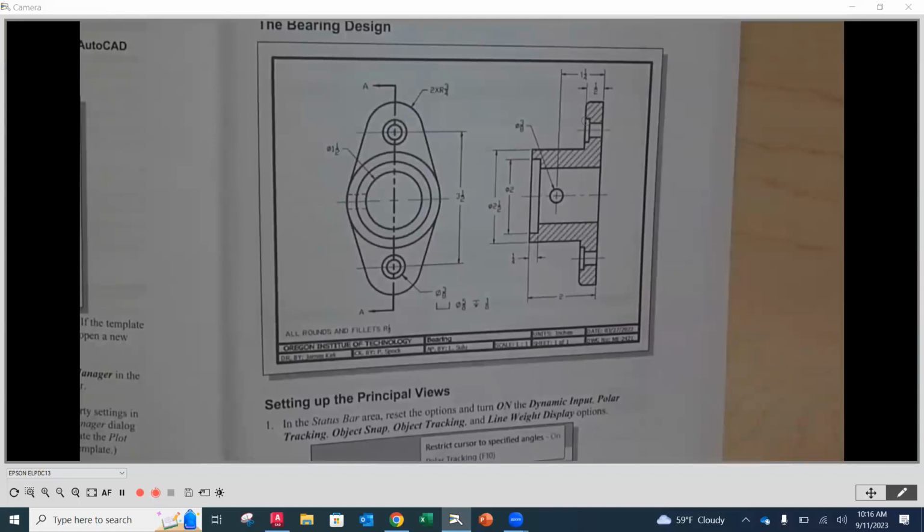Those counterbores, as I look across, the callout is right here for me. It says a diameter of 3/8. That's going to be the through hole, the smaller hole that goes all the way from one side to the other. And then it says a counterbore symbol here, and a diameter of 5/8 or 0.625. That's going to be the wider one. Now we have a depth symbol. This is that depth symbol, the horizontal line with the arrow going down. That counterbore is only going to be 1/8 inch deep. So that's going to be the offset in.